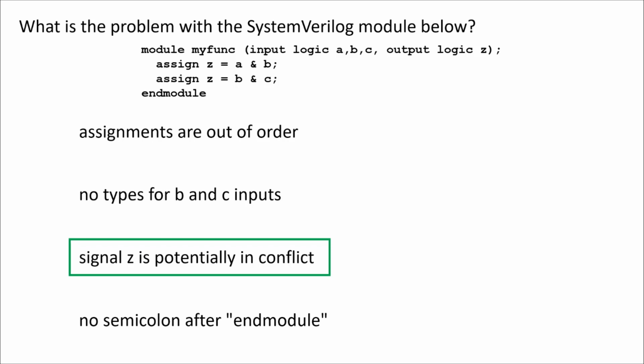It means that there's a high impedance between that signal and power and ground, I should say. In other words, when you use a transistor to pull up or pull down a signal to power or ground to make it 1 or 0, you're providing a low impedance to power or ground. High impedance means I'm not pulling it anywhere. It's just floating. If you measured its voltage, it would be indeterminate.